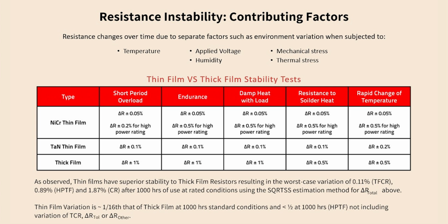Thin film resistors provide far greater stability under stress compared to thick films, making them the preferred choice for high reliability applications where minimal resistance drift is critical.